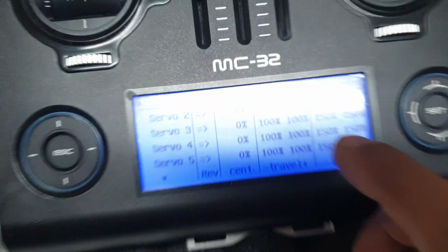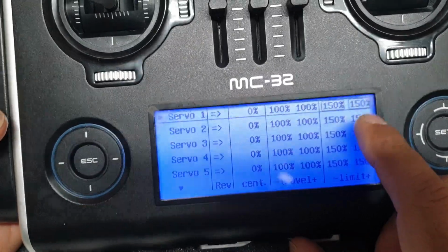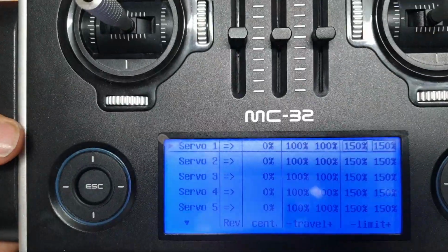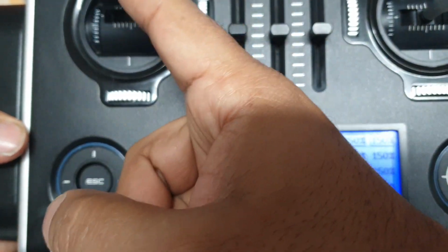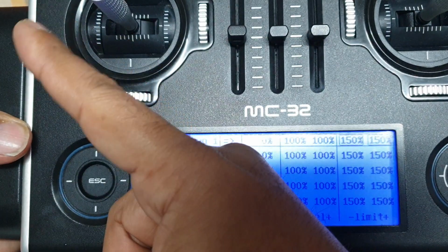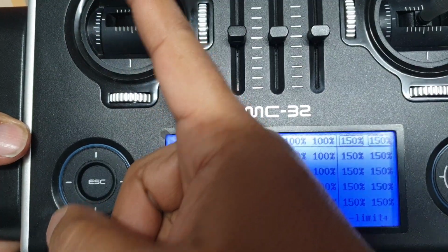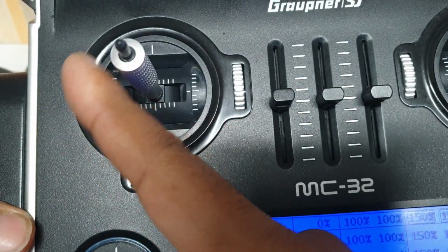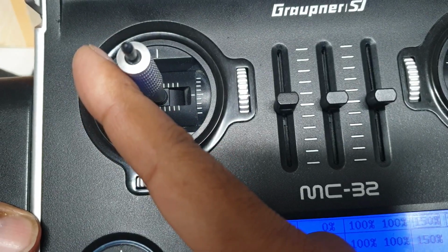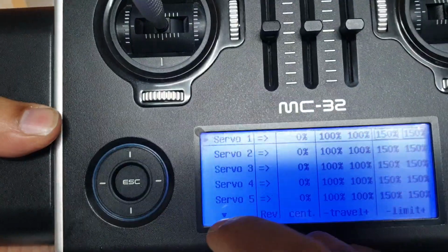and that is good enough for my servo travel. So that you can adjust over here, and that's what it actually means when I say you don't want to be physically pushing your servo against it, because it's going to bring no value. The servo can travel all the way, but I don't need it to travel all the way. I just need it to travel up here, and hence you will set it up over there.